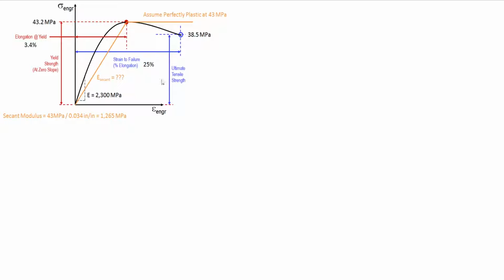And then finally we have the ultimate tensile strength. In this material, it is a lower stress than the yield, but in steel, where the graph goes like this, and then comes down, and then goes back up, quite a bit higher than its first point when it goes into plastic deformation, then that's a significant point, because that is actually your UTS, your ultimate tensile strength.